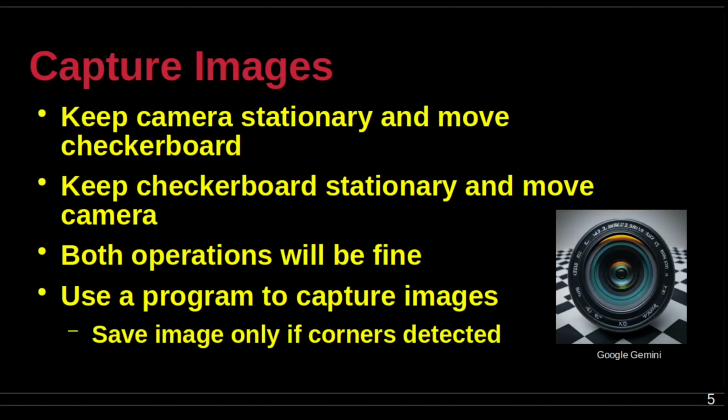For the very limited purposes of this tutorial, approximately 30 images were captured for each of the two cameras on the Tello Talent drone. It is good practice to check for corners in a captured image before saving it for further processing. If no corners are detected in an image, in other words, the connection between the detected corners is not overlaid in the display window of the captured image, then that image will not be useful in calibration calculations. Therefore, it should not be saved any further.